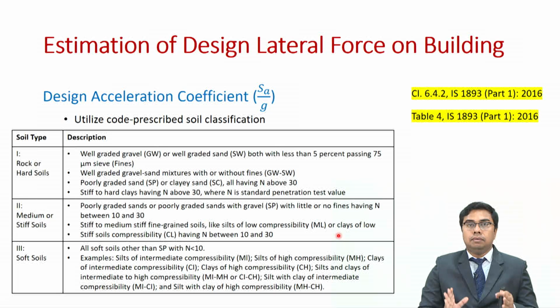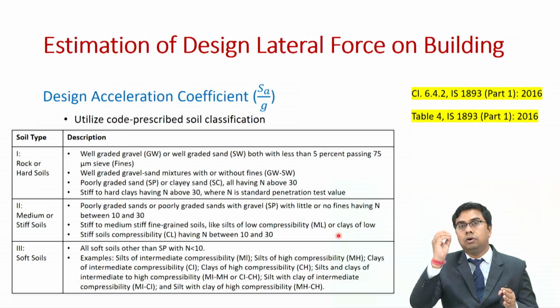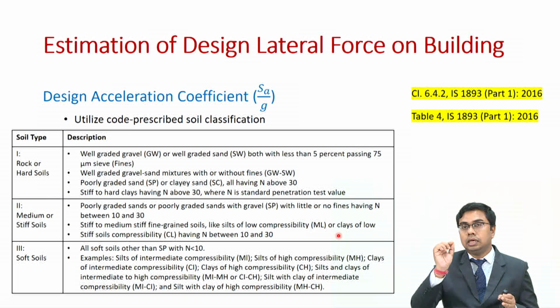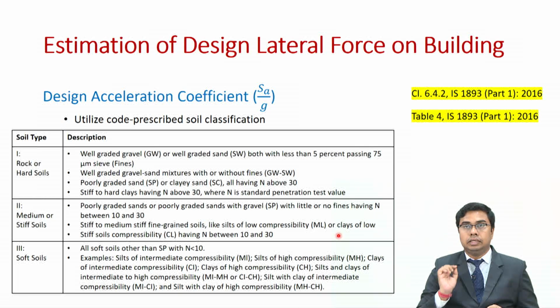After finding the design base shear, it is time to find out what shall be the lateral forces being applied on various floor levels. How shall we find that? Or in other simpler words, we need to distribute the design base shear at different floor levels.